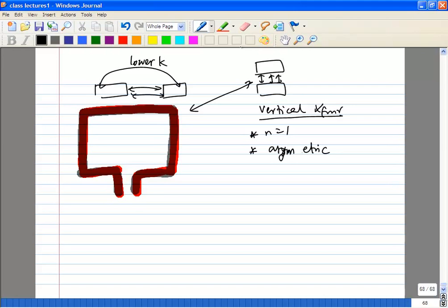Why is it asymmetric? Because the primary is on M6 and the secondary is on M5, right? So there's going to be a difference in resistivity, a difference in capacitance, a difference in losses, a difference in everything. If you are not interested in the symmetry, then this is the way to go.